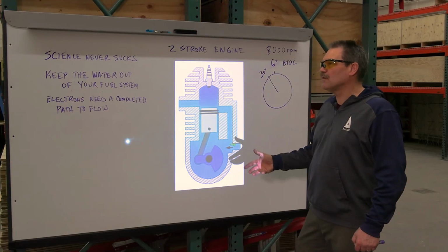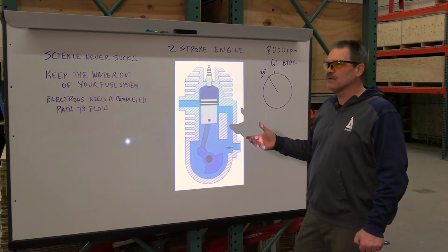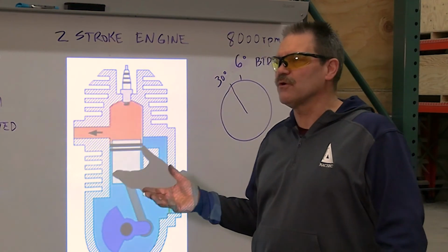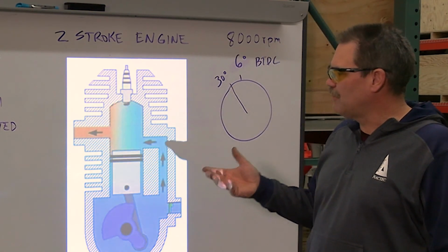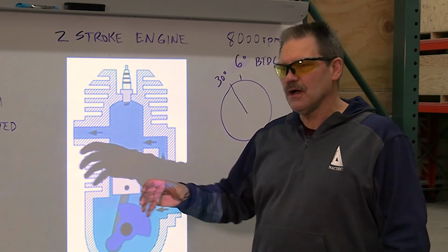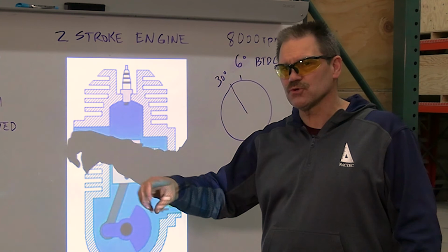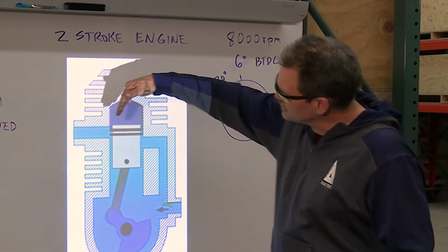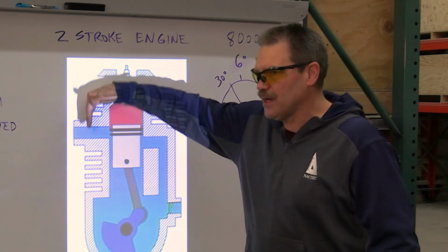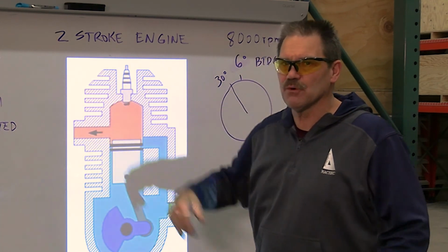The RAVE valves for the Rotax engines use pressure difference. Some of the other makes and models, I believe some of the Arctic Cats, actually have a sensor on the throttle and it's controlled electronically. What's in there is like a big guillotine that opens and closes depending on the RPM of the engine to make the engine more efficient.